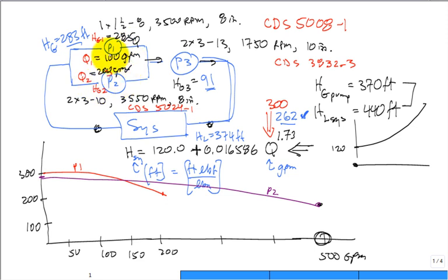Actually, what you can do is, isn't Q2 equal to Q3 minus Q1? Yeah, they have to be consistent. No, I'm saying, should we divide that to 150? Oh, yeah, that's the question I was asking. This is the head gain across pump 1, that's the head gain across pump 2, they have to match. They have to both be 283 foot head gain. We calculated Q3 to be 262. We just did Q1 to be 109. You find that the Q2, just by volume balance, is 153.